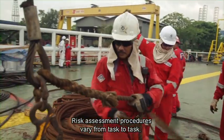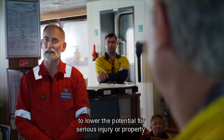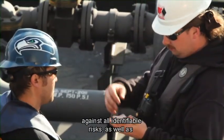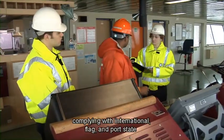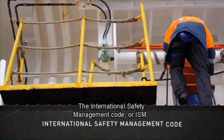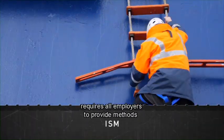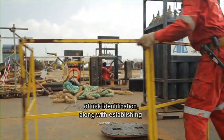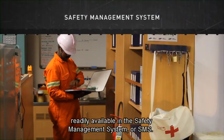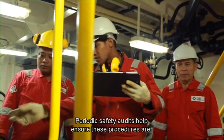Risk assessment procedures vary from task to task. They include evaluating unavoidable risks in order to lower the potential for serious injury or property damage, along with creating safeguards against all identifiable risks, as well as complying with international, flag, and port state regulations. The International Safety Management Code, or ISM, requires all employers to provide methods of risk identification along with establishing the safeguards to reduce risk, and have them readily available in the Safety Management System, or SMS. Periodic safety audits help ensure these procedures are working properly.